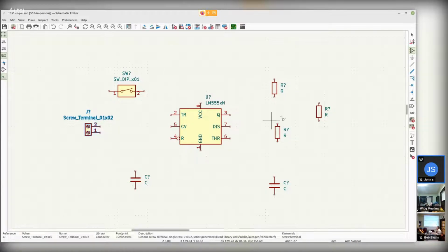And to wire, I could go over here and click on the wire button here, or I could add a bus if I have a bunch of wires that are all going to be connected. Because on the schematic, say you have a bus of 5 wires, instead of having to draw all 5 wires, you can define a bus that you can connect in, and then it'll sort of neck down to the bus symbol, and then you can pull it over to somewhere else in your schematic and have it explode out. So that kind of lets you logically separate stuff and show that, oh, there's a RAM bus that runs here with 20 wires. I don't need to see all 20 wires as long as they're properly exposed at each end.